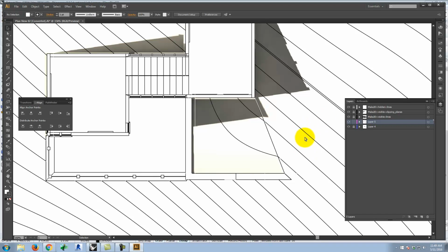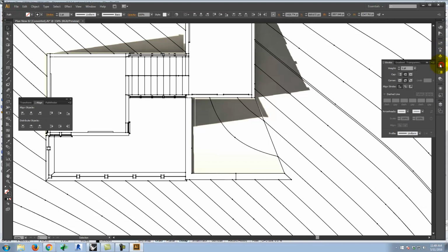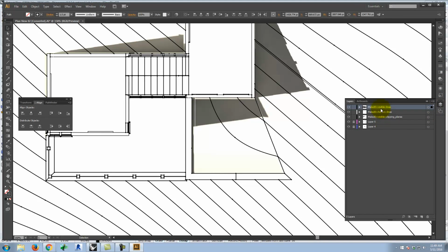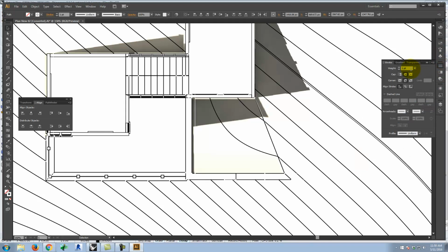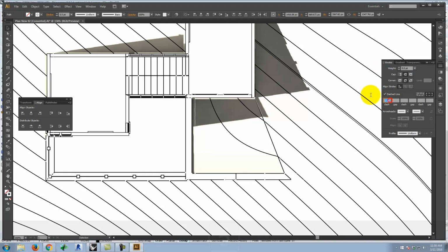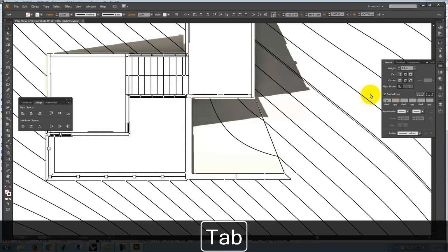And then I can go through and select each of my line types here. We'll move my visible lines to the very top. I'm going to select all of them and change their line weight. I don't know, maybe 1.5. I'll take my hidden lines, and we'll select all of those. And I'm going to go to my line types. We'll make them 0.5, and we'll do them as a dashed line. I'm going to do them a little finer than last time. We'll do 2 point and 1 point.